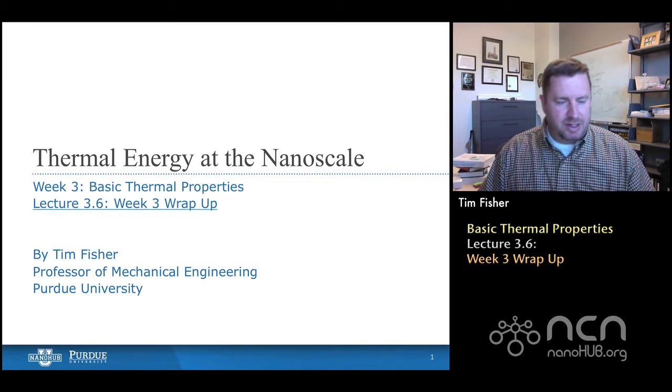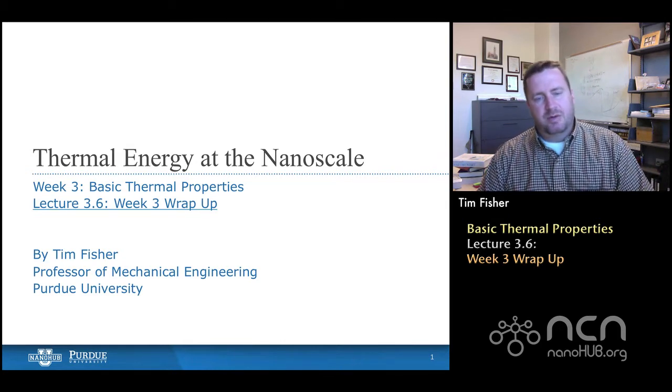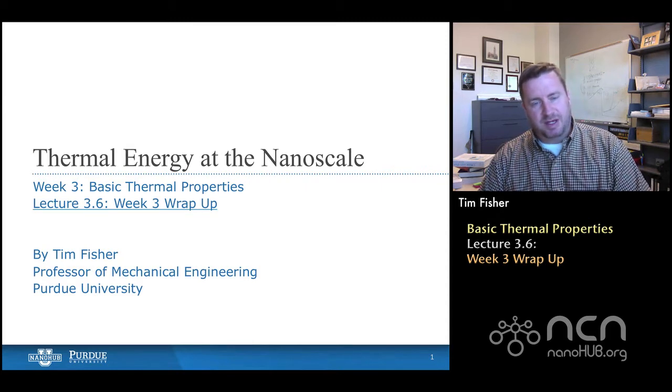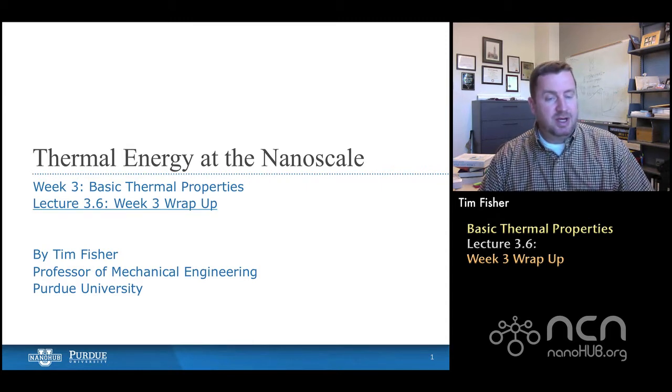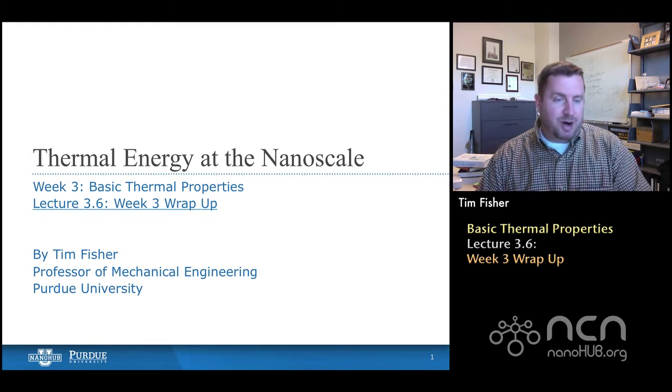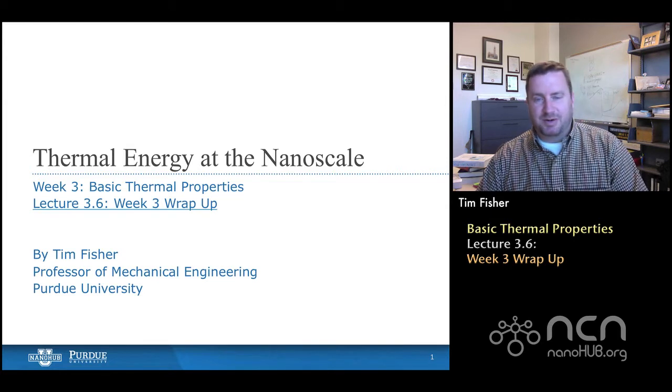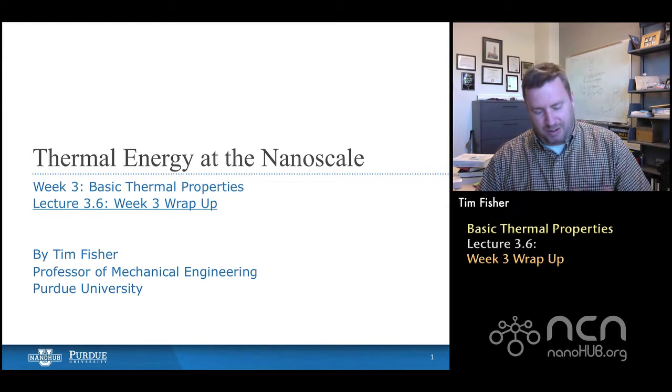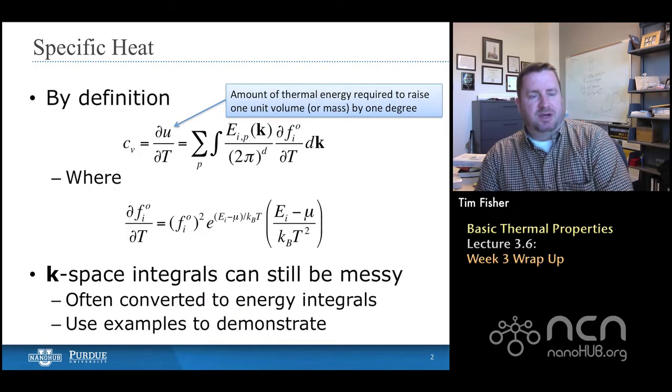And what we tried to do in week 3 was to derive some basic thermal properties, and preeminent among them is the specific heat. We had to do that for different kinds of carriers, and within carriers, for example within the phonons, we used some different models. By the end of the week, through the help of kinetic theory, we used the specific heat in the definition of thermal conductivity, which is the superstar property for thermal transport, right? That's the one everybody usually wants to know. And we've made a lot of progress, I hope, looking at that specific heat definition.